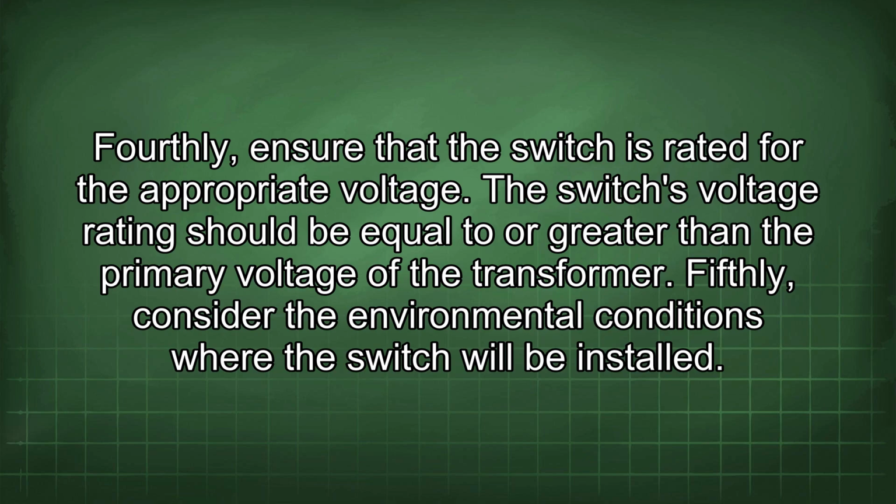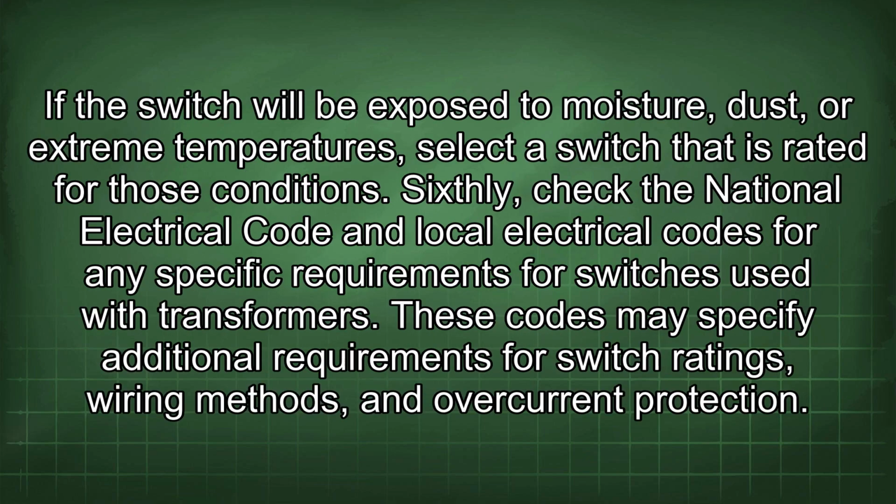Fifthly, consider the environmental conditions where the switch will be installed. If the switch will be exposed to moisture, dust, or extreme temperatures, select a switch that is rated for those conditions. Sixthly, check the National Electrical Code and local electrical codes for any specific requirements for switches used with transformers. These codes may specify additional requirements for switch ratings, wiring methods, and overcurrent protection.